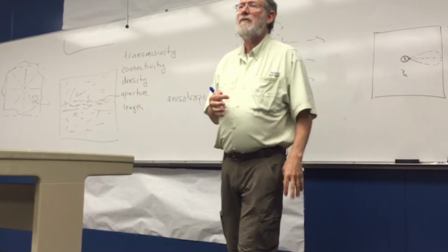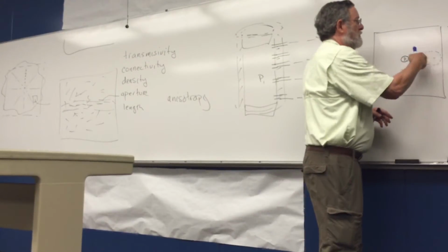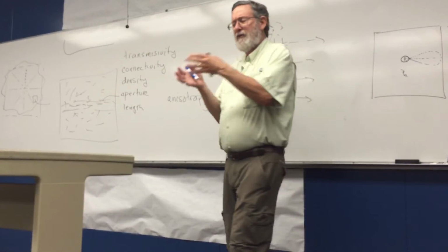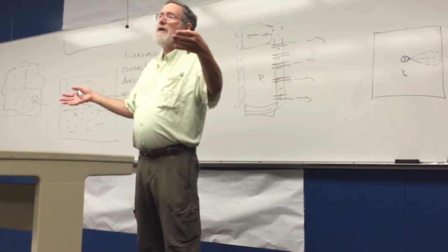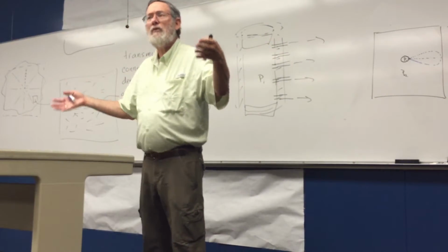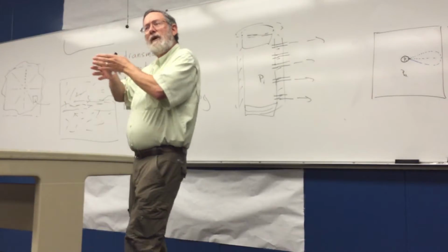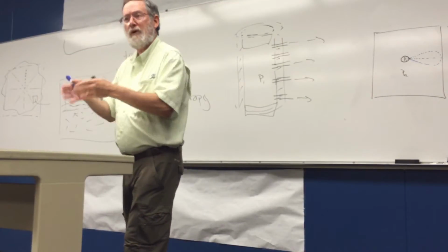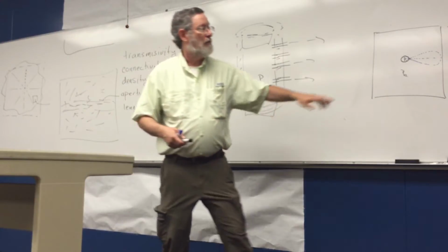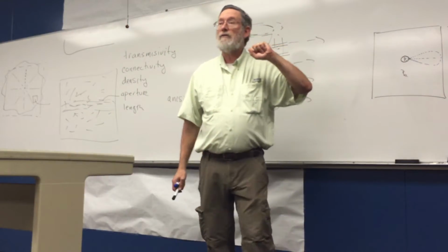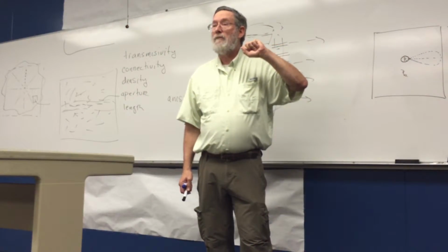It leaks. And so this would be representative of the volume of fluid that I have lost into the formation, because it's a porous material and I'm operating at higher pressure than the pore pressure of the fluid. And so that's the volume that I've lost in the system.